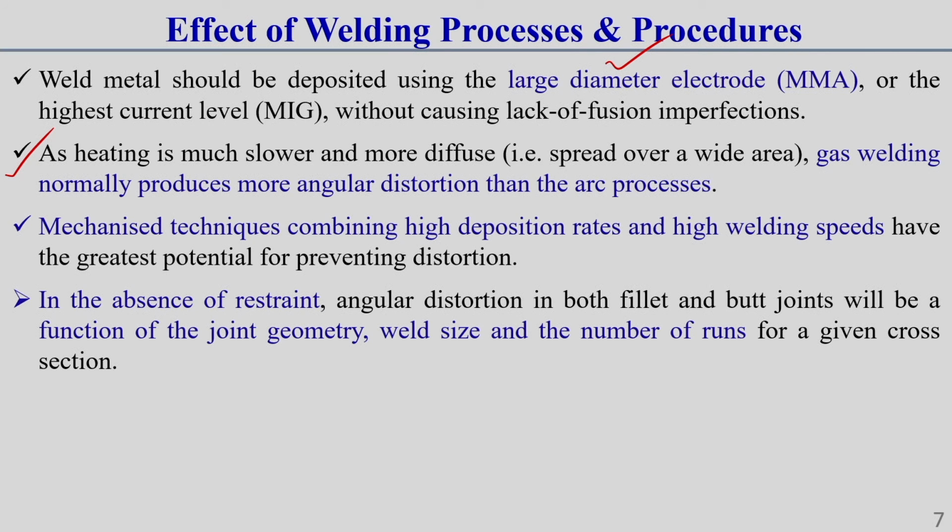During solidification, due to this wide heating zone in oxy-fuel gas welding, there is a chance of wide expansion and contraction and more deformation than in the arc welding process, because in arc welding we generally get a localized or concentrated heating source.